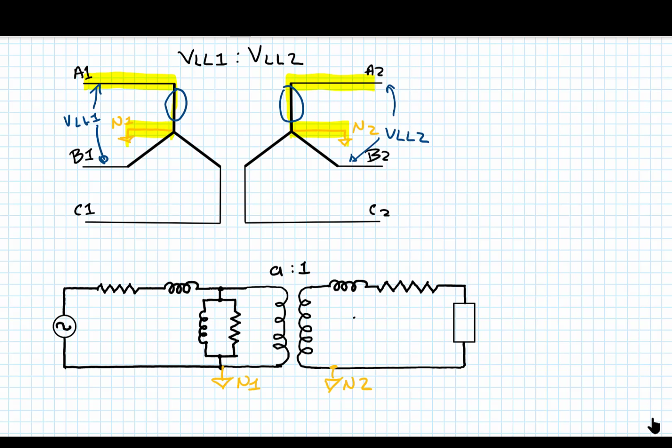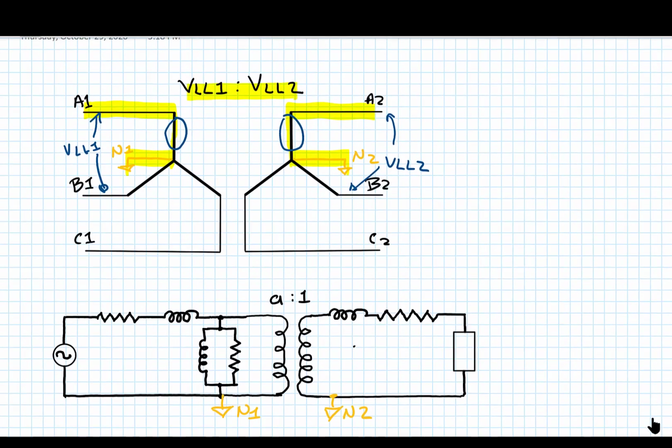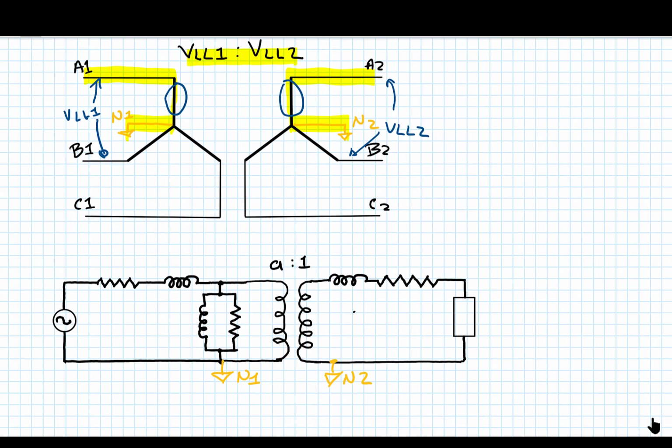Now these voltages are a function of whatever the upstream voltage is that we are applying to the transformer. They're not the same as this. This is a transformer voltage ratio that's fixed according to the transformer rating. So I can, because I know these line-to-line values on each side, define a line to neutral on the primary and a line to neutral on the secondary.